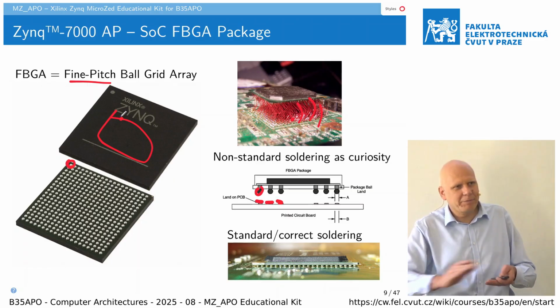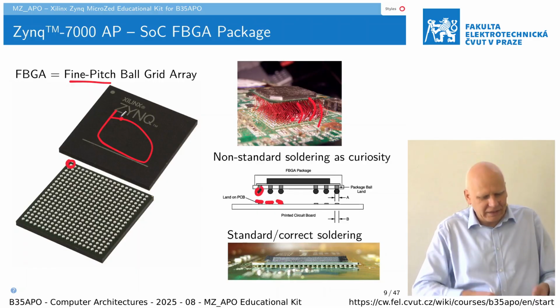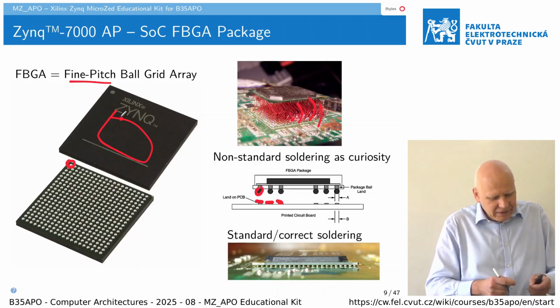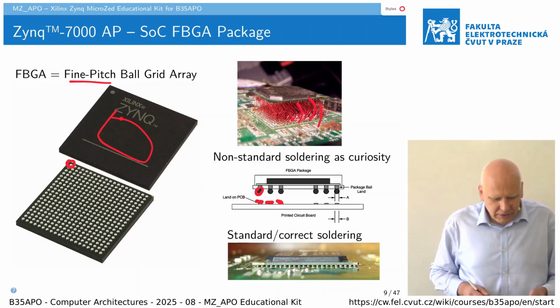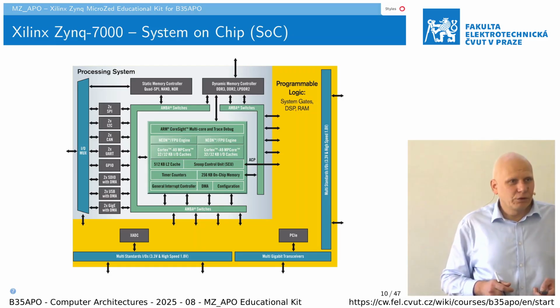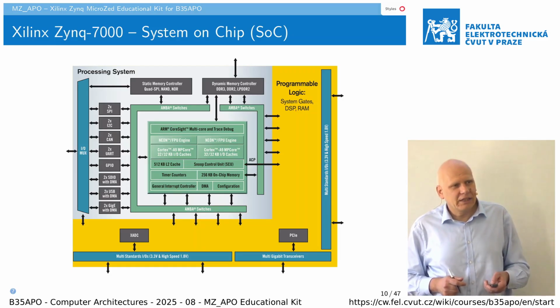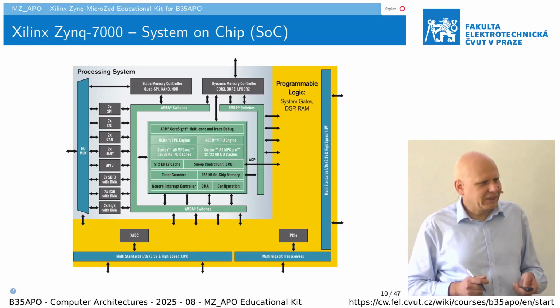So basically strip away the remains of the soldering and rebuild new small balls, and it is not so easy. But one of my colleagues has succeeded with a graphic chip to solder it this way in his hot air oven at home. So sometimes there are options, yes?